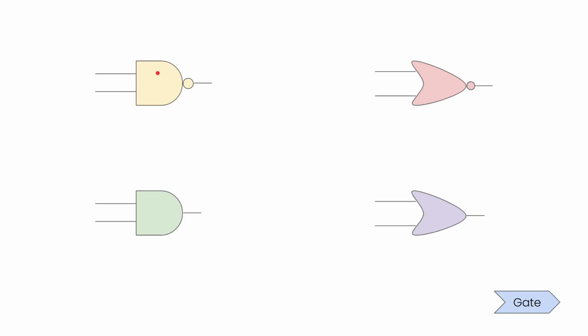And if you ever look at transistor level design, which are the transistors that are connected, say, to enable this to turn into this, with some styles of designs, you're literally adding an extra gate to go from a NAND gate to an AND gate. In other styles, you can get both at the same time. There's not much overhead, but the design is complicated, and you have to make sure the transistors you're using are sized right.